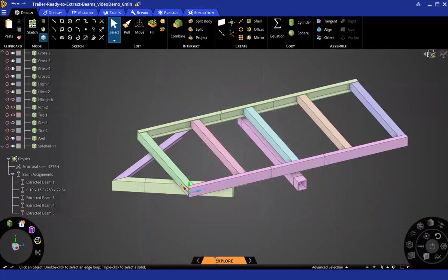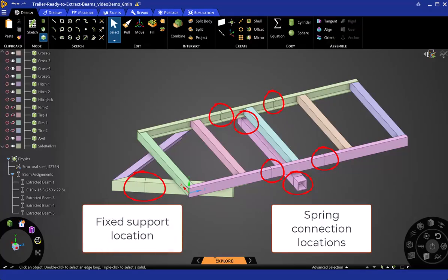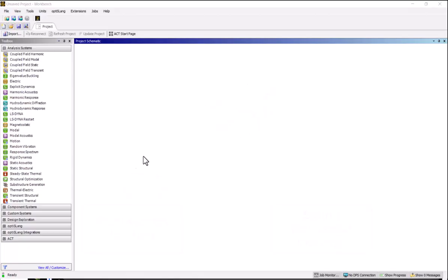The Ansys model that we are providing for the walkthrough example will already have the wheels and the hitch jack excluded and beams split at the specific locations, and it looks like this. Let's get started. Insert a static structural system into the project page. Import the geometry.